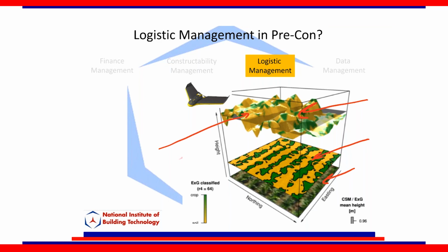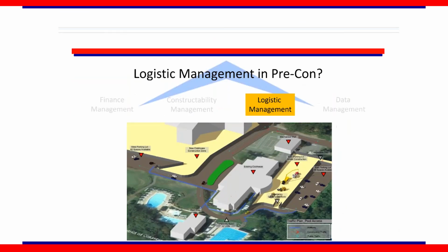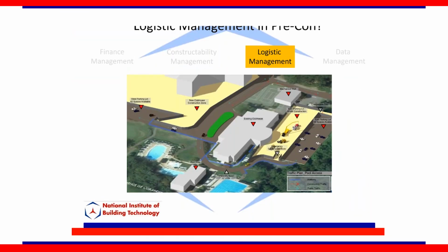The only thing is you can only fly drones over a pretty large area. You cannot fly them through the buildings. So the scanners I showed earlier are more used in the interior of buildings, whereas drones are used even for the building exterior. If you fly a drone around the exterior of the building, it will map the building every day and will show video analysis of how the building was actually built in point cloud. So drones are used for exteriors mostly and site logistics mapping. Okay, excellent tool.